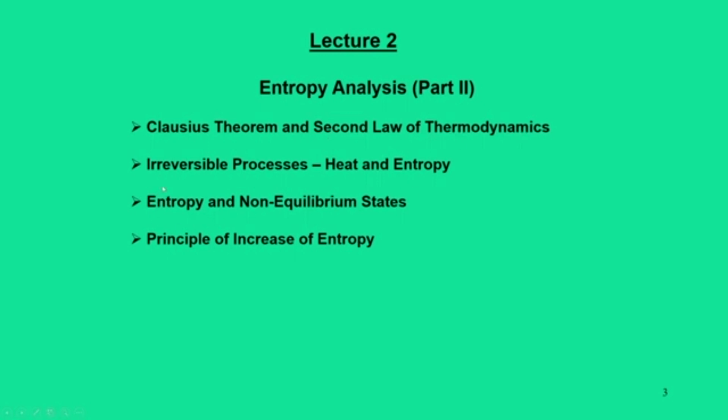The Clausius theory, as in the previous lecture, considers the entire cycle in terms of segments, where the closed reversible path is replaced by a closed but zigzag system of isothermal and adiabatic processes, each one a Carnot cycle, many Carnot cycles for this closed cycle.